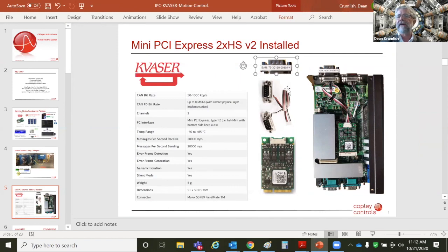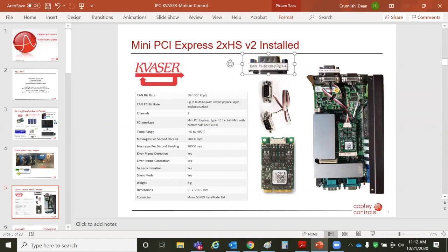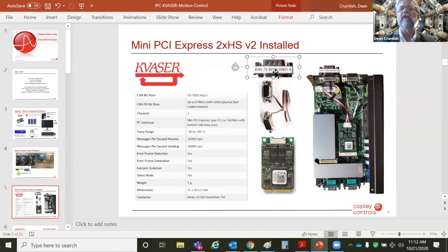I've got to ask the audience, you guys sell this, right? Maybe Tammy knows. Yeah, we do. This is Jesse over at Kvaser. Yeah, we definitely sell those. They're not very expensive, but extremely useful. Yeah. So it's got 120 ohms in it, and it's nicely packaged, so it's very convenient. If you want your CAN network system to work properly, you've got to have termination at this end. So get yourself one of these for a properly terminated CAN network.